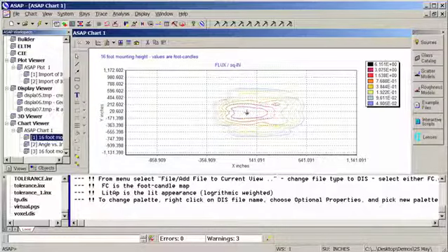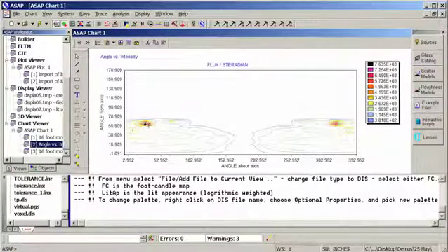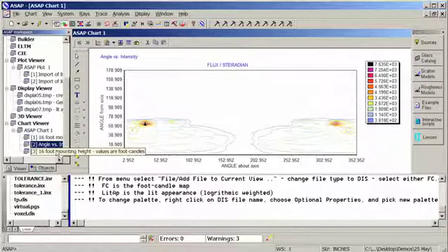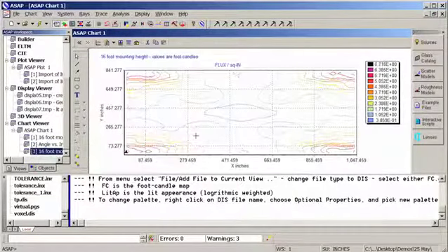The black triangle indicates the point of maximum intensity, and we can look at this in flux per square inch, so we're looking at the energy across an area. We can also look at it in terms of an intensity versus angle plot. We can do plots in direction cosine space, and this is again the same contour type plot, but in this particular case we've added the 4 street lamps, and this is that dark zone between the lamps.